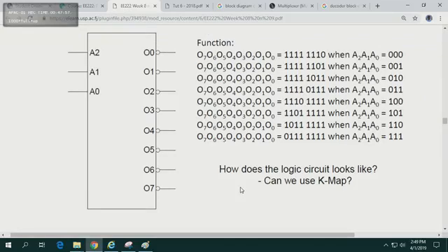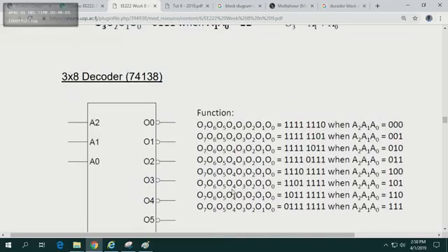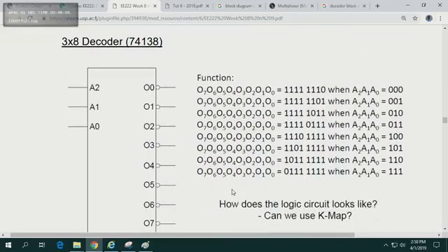Oh, by the way, one more thing I wanted to mention. The naming convention, guys. Can you see over here, the naming is 2 to 1. With a multiplexer, with mux, the name always has 1 at the end. The second digit is always 1. Why? Because there is only one output. Now with a decoder, it's always input dash output, right? So 3 dash 8, 3 by 8: 3 inputs, 8 outputs. And in mux, it was data lines to output, right? So 16 dash 1.